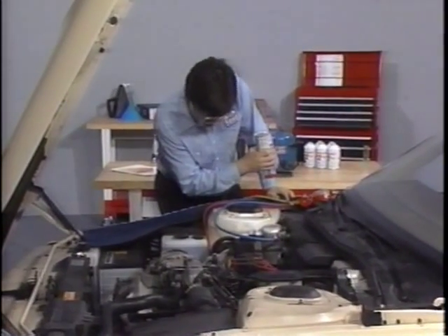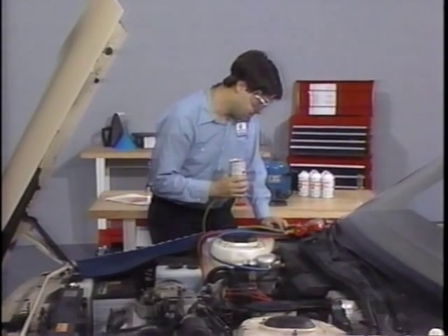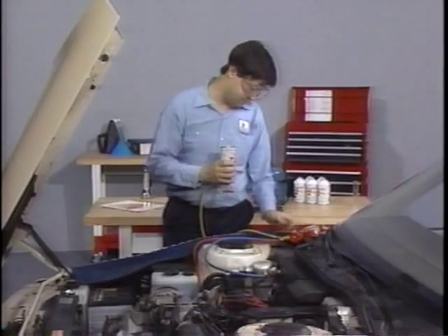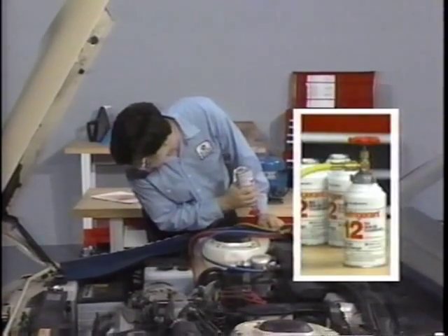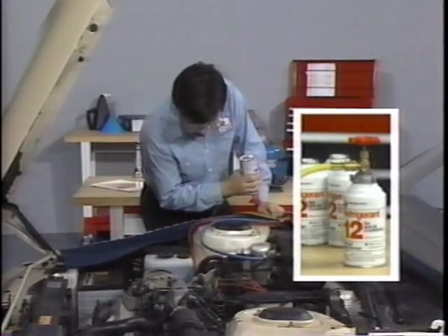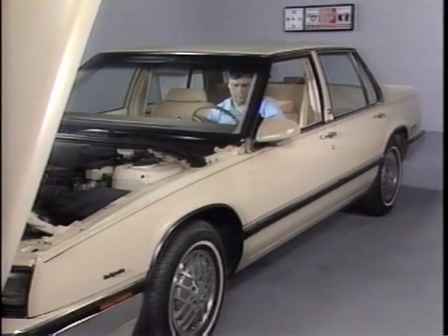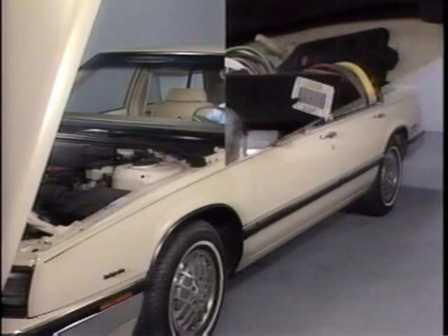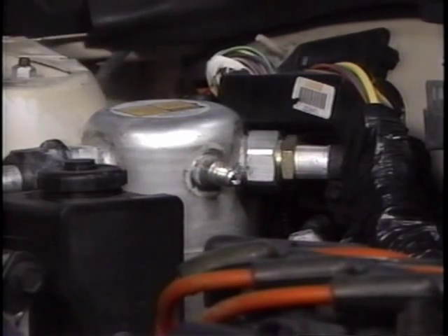If you are using a charging station, follow the manufacturer's instructions, with the exceptions noted in the Buick Chassis Service Manual. After discharging and evacuating the system, begin the flushing procedure by adding 2 pounds of R12. Do not use any other type of refrigerant for this procedure, or you could damage the system. Run the engine at idle for a minimum of 5 minutes with the air conditioning controls in the max AC mode and the blower on high. You can then discharge the system.